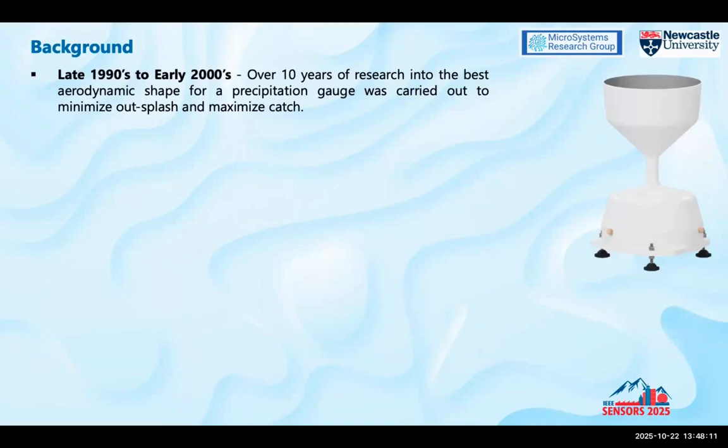The background of the work that we've done over the last 25 years is in the late 90s and early 2000s, we did over 10 years of research into best gauge shape design. And this is the shape that was come up with that was the best. It's a combination of how high this area is, so you don't get outsplash of the rainfall as it falls into the gauge. But then you've also got to have the aerodynamic shape to push the wind underneath the catching area, so you reduce the amount of wind that goes across the top. So this is the design we came up with.